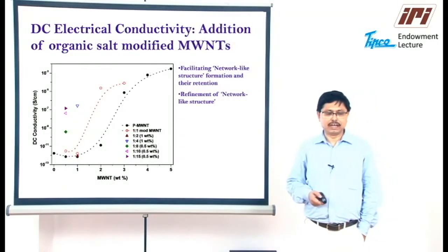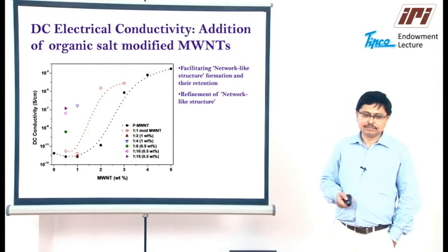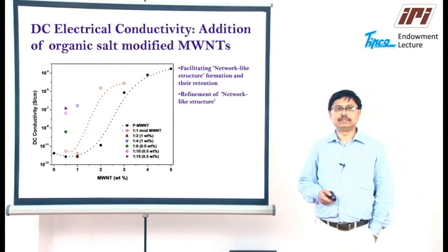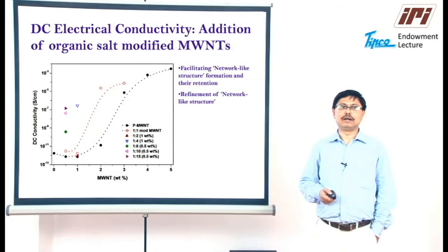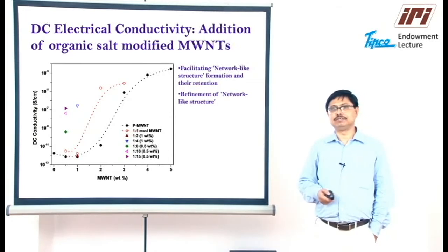One can also find the DC electrical conductivity in the presence of the various mixtures of multi-wall carbon nanotube and NaHA in the polyamide 6 matrix, and even at 0.5% the materials become at least dissipative in the conductivity range, and the percolation threshold actually shifted towards 0.5%.